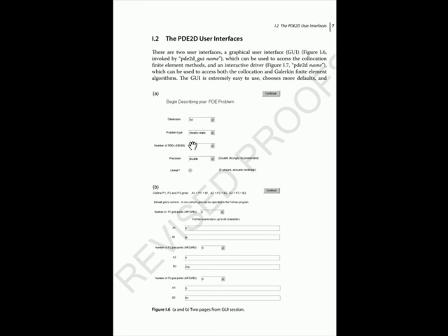And here's an example. The first couple of pages of the GUI, it asks you what's the dimension of your problem, is it steady state, time dependent, or eigenvalue, how many partial differential equations, and so forth. And then there'll be 10 or 15 pages where you supply information. It's relatively easy to use, but only for the collocation method. So you'll have to define your x and y, or x, y, and z in terms of the parameters and give the limits on the parameters and so forth.